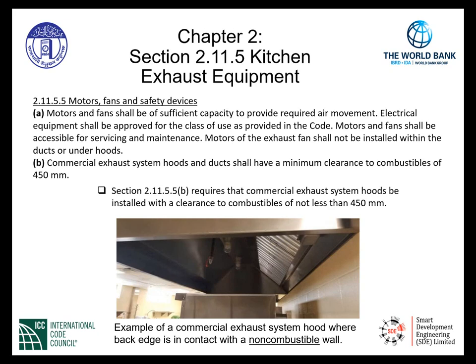Motors, fans, and safety devices are given to us in section 2.11.5.5. Item A, motors and fans shall be of sufficient capacity to provide required air movement. Electrical equipment shall be approved for the class of use as provided in the code. Motors and fans shall be accessible for servicing and maintenance. This is so important regarding these type of systems. Motors of the exhaust fan shall not be installed within the ducts or under hoods.